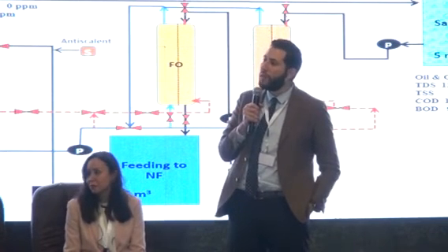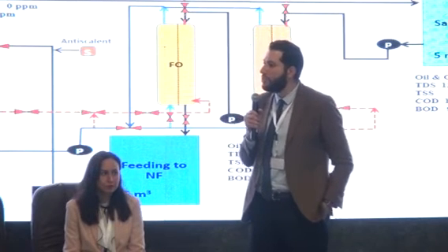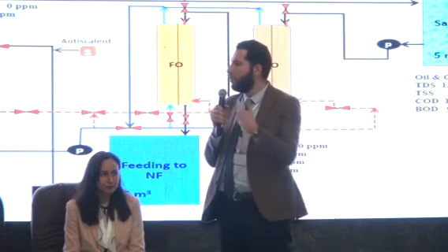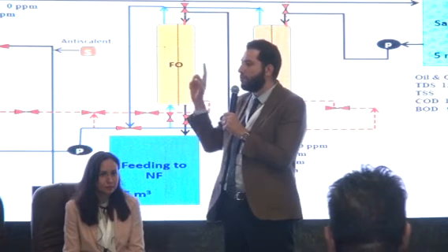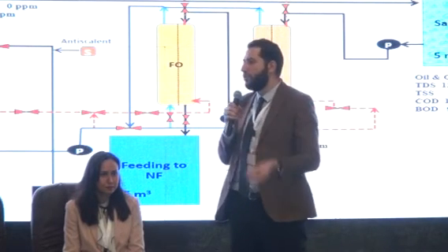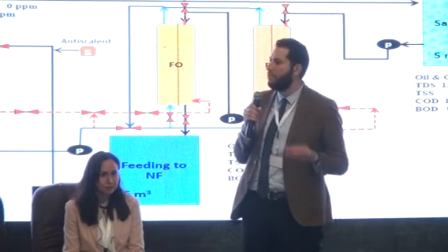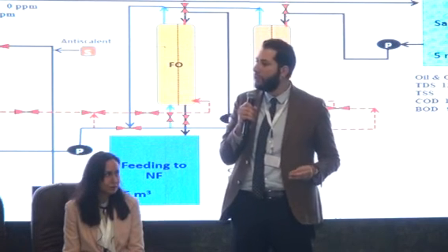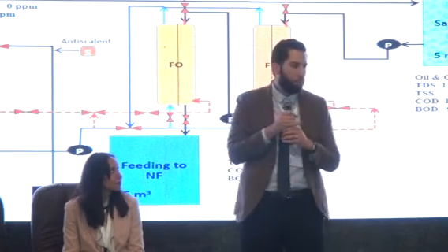This is designed for 97% conversion. And we've licensed 7 units, all starting up in the next few years. So after this one in China, there is another one in Europe in 2022. So to answer your question, yes, UOP has technology that can convert fuel oil at 97+% conversion.